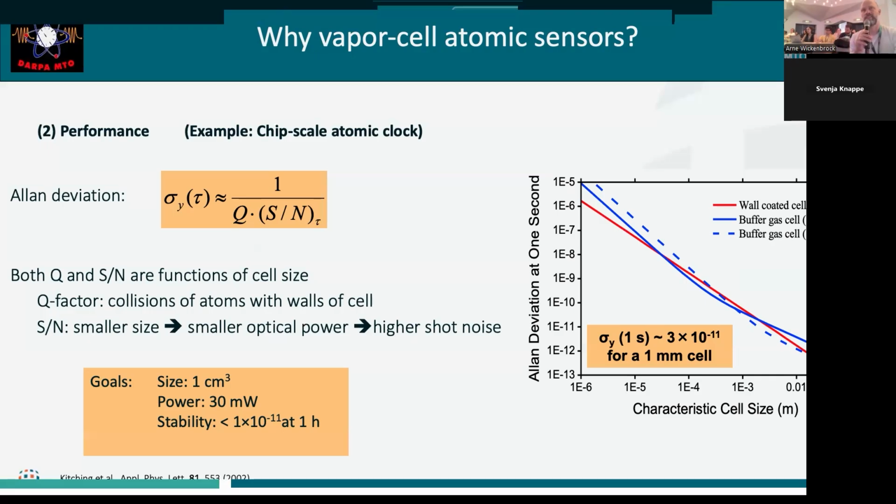And what's the output basically? I mean, just time, digitized digitally. So it's a stable frequency that comes out. In this size, the frequency unfortunately was in the gigahertz range, which is not what the user wants. They want a clean 10 megahertz, no modulation, and so on. And so that's where the difference came in when it was commercialized. They made it about 4 times as big, so 4 cubic centimeters-ish, and they added these frequency converters to get a stable 1 PPS signal. So 10 megahertz clean signal out. So they locked it to an external oscillator again.